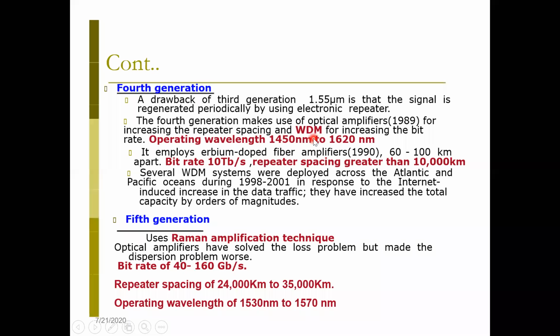You might have heard of time division multiplexing, frequency division multiplexing, CDMA, and so many things. In fiber optics, the multiplexing technique is wavelength division multiplexing. As you know, in fiber we are not using the term frequency. We talk in terms of wavelength. So multiple wavelengths, we multiplex them together and then we send them through the fiber.